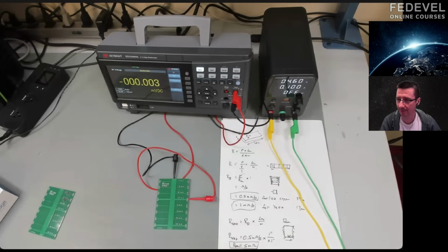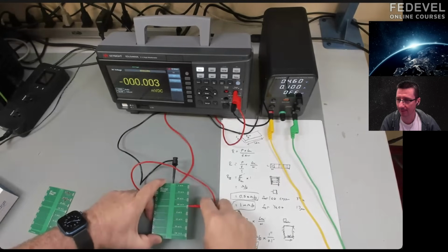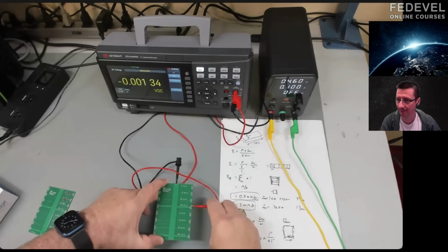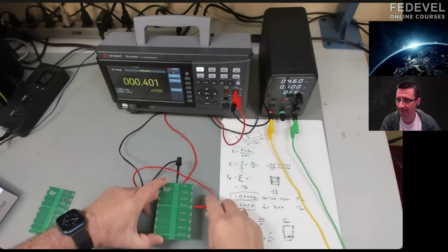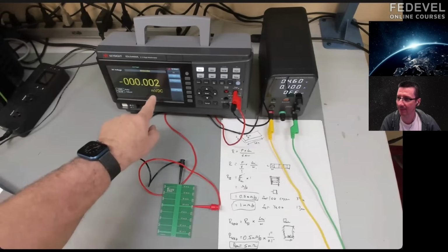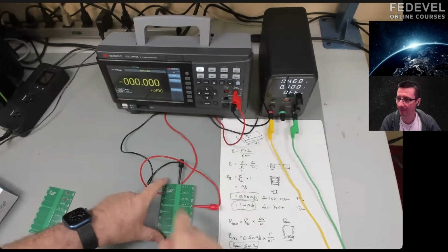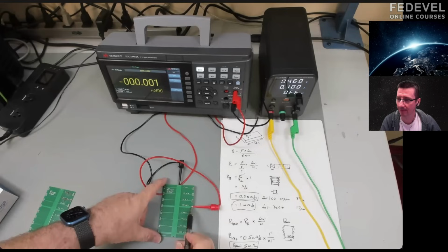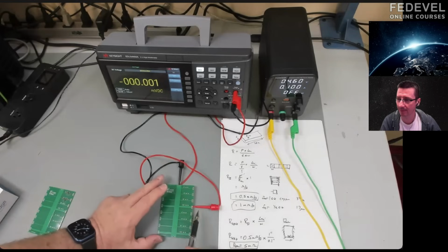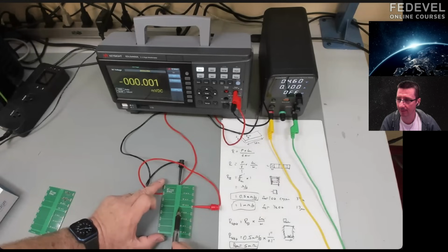So let's measure it. I've instrumented this board so we have little holes to clip the leads. I've got my digital multimeter set for volts right now. We're going to change it to ohms and measure that resistance. We're going to measure here and then this piece over here. I'm lying a little bit. It's 5 milliohms for this. And then what's this going to be? Now we know the trick.